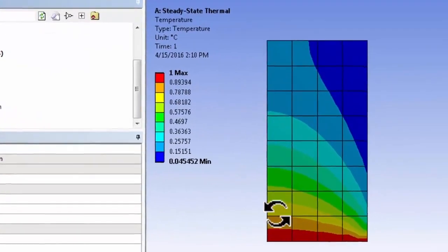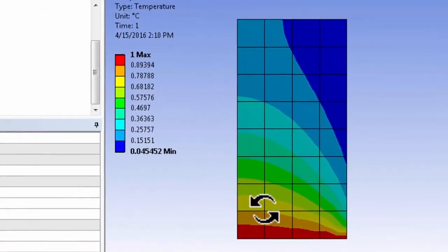What it did was it went to get the temperature value at any arbitrary location. It's just doing an interpolation from the 8 surrounding nodal values, and that's quick, as opposed to having to invert a stiffness matrix, which tends to be the most time consuming part.